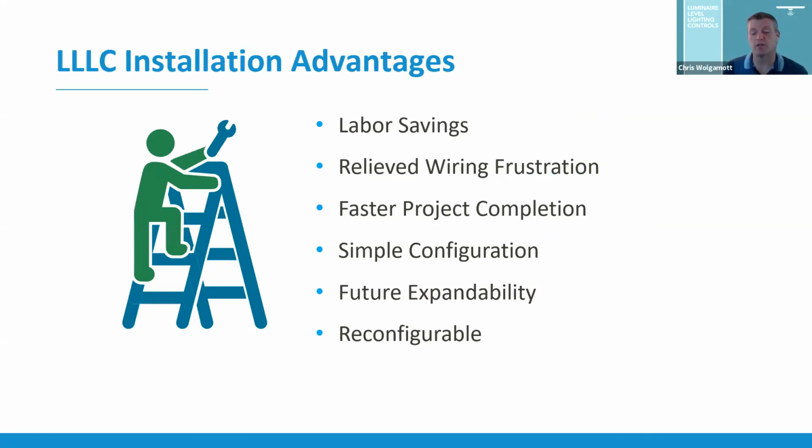Yeah, great. So you can see where there are cost savings in the design portion of it. Now let's talk a little bit about some of the cost savings that show up on the install side. I think the biggest thing, and we talked about it a little bit, is the wiring, but that is huge when it comes to labor. Everybody knows how expensive the electrician is to do the wiring pieces, to run 0 to 10 volt wires for the controls. We don't have that cost in this because all the controls are wireless.